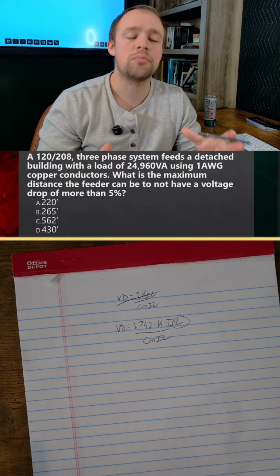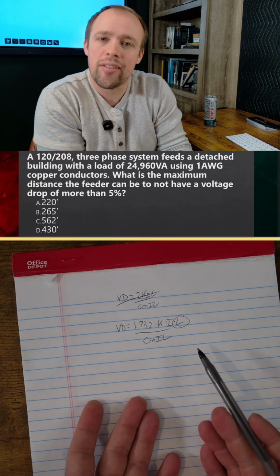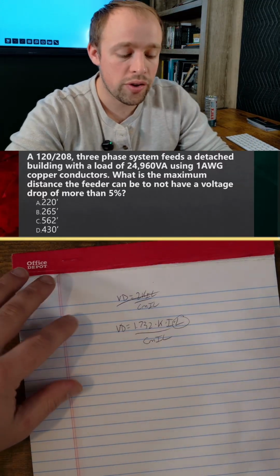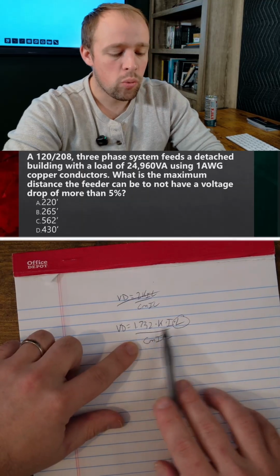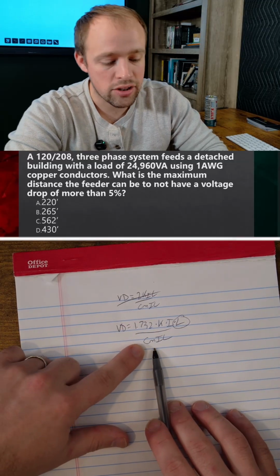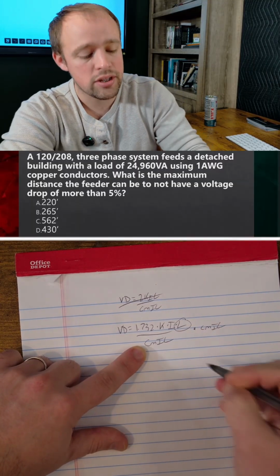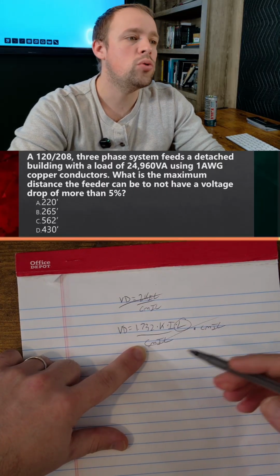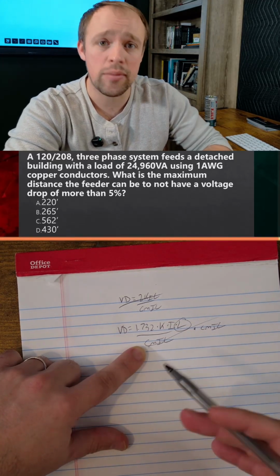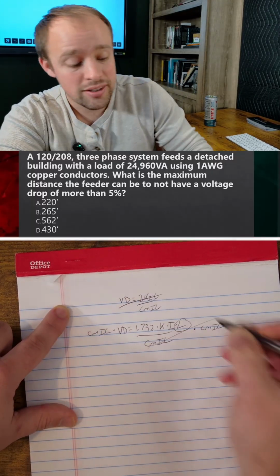So we need to use basic algebra, which we cover in chapter 2 of our book, so that you can take a formula like this and rearrange it to solve for L rather than for voltage drop. The numerator is being divided by our circular mills. How do I get rid of that? If it's being divided, we multiply by that same circular mills to cancel it out. However, what you do on one side of the equation, you have to do on the other side to keep the formula true. So I'm going to multiply by circular mills on this side as well.